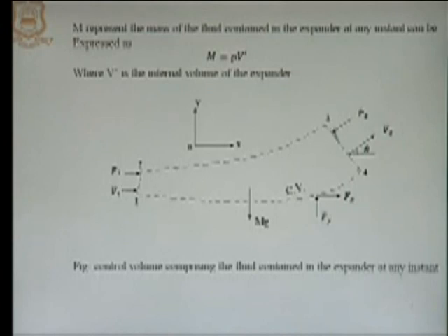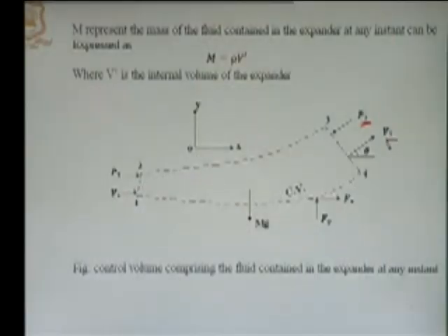At this section, this fluid was in contact with another fluid where pressure force is equal to P2. Now, this P2 and P1 we know always act in such a manner so that they compress the fluid. Now, at this end 3, 4, this fluid is leaving with velocity V2, and this angle theta is also given to us as per the shape of the bend.